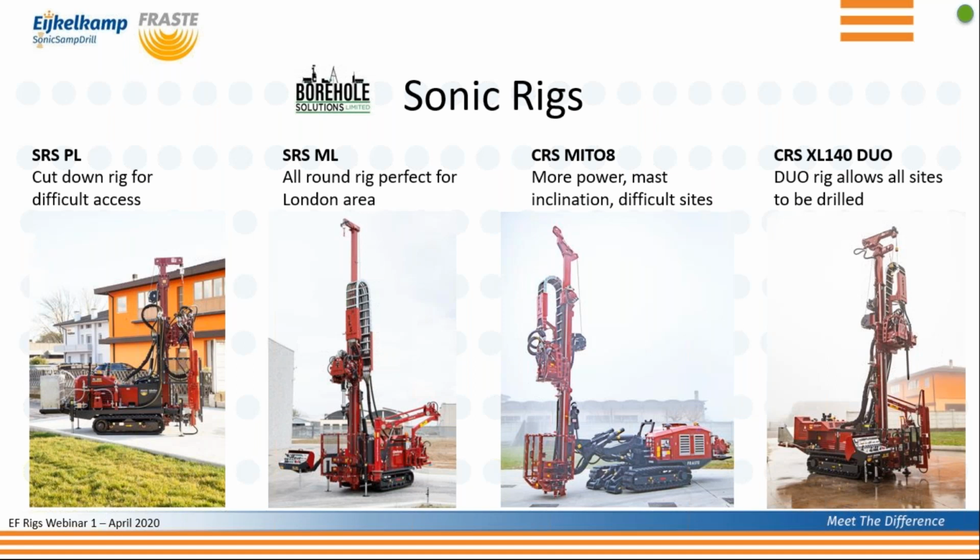Okay, so there's no need for this geobore. There's no need for this cable percussive to start the hole and then get a rotary to pull over a cable hole. It eliminates all that messing around. You just do it with one rig and get 100% recovery all the way down. Okay.